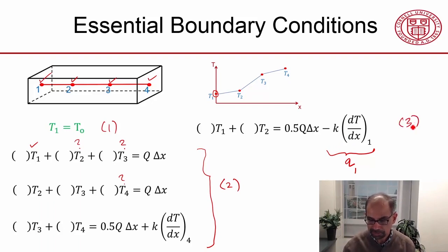So in the 3rd stage, you can come to this equation and say, hey, now I know T1 and I know T2, and this is a known quantity, so I can determine the flux at the left boundary. And if I take Q1 and multiply it by the area, that's the amount of heat flow leaving or entering through the left boundary. And I can do a check on the solution, whether the solution satisfies the heat balance or energy balance.